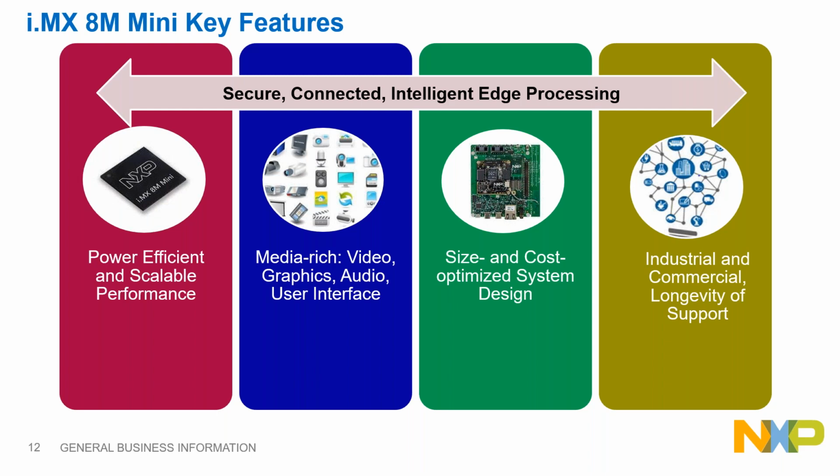Enabling these features in a 14 by 14 millimeter package size that allows you to route into a 6 to 8 layer board, and a range of memory choices covering DDR3L, DDR4, low power DDR4, enable the Mini to be applicable to a wide range of different verticals, both consumer and industrial. The industrial qualification and NXP longevity program enables designers to utilize these parts for all of these key markets.